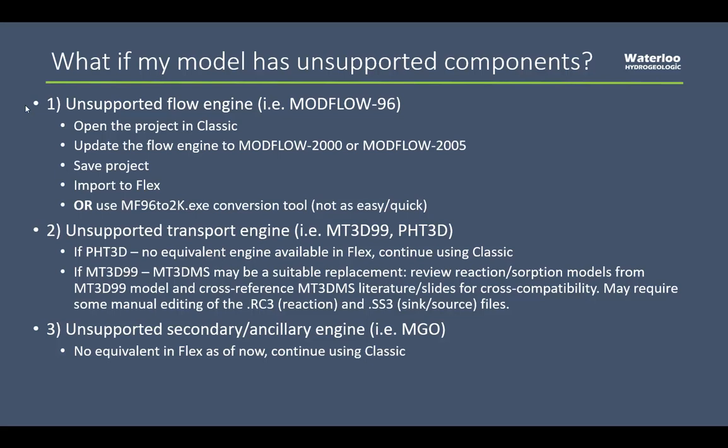You can then close the Classic interface, open up Flex, and at that point you should be able to import the project without any issues. So it's simply a matter of converting that MODFLOW 96 project to a MODFLOW 2000 or 2005 project using VMOD Classic. Now, if a Windows 10 update has come along and has essentially made it impossible for you to use